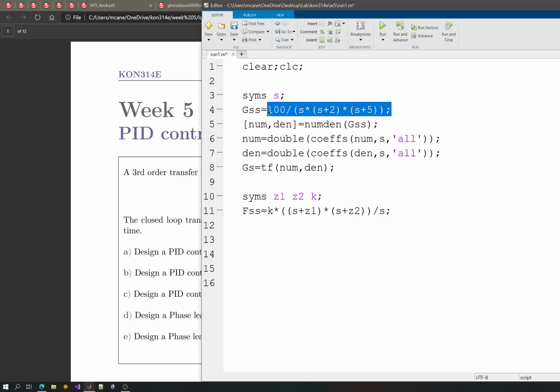And think about this. If you are trying to cancel something that's on the origin, and especially at the origin, and if it's a pole, and if you're placing a zero on top of it, what will happen if you have a slight error in your model? Basically, it might end up on the right-hand side, and that's why it's called marginal.